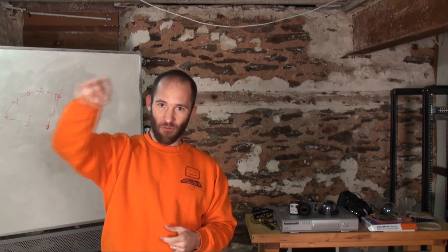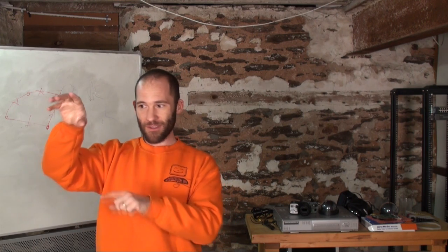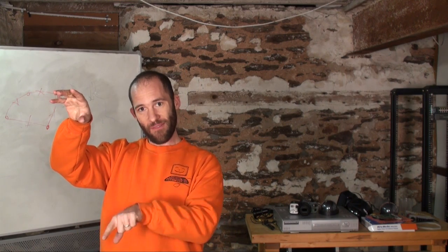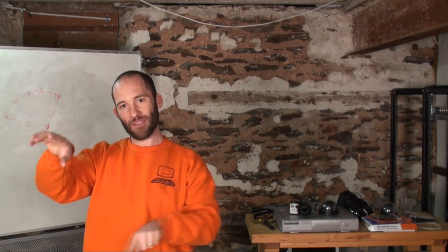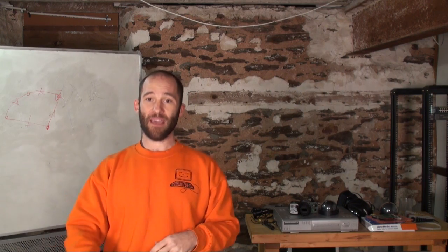Again, as I talked about with analog cameras, I hate PTZ. Remember, it's a ring formation for the cameras, so the wire has to go from the DVR to the first camera, to the second camera, to the third camera, to the fourth camera, etc. If there's any break in those controller wires, none of the cameras work. It's just evil. You have to have a controller in the DVR. That controller has to speak the protocol that the camera is going to understand. There's a lot of these protocols out there.